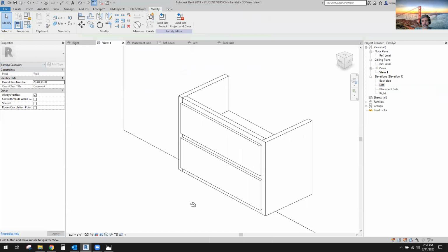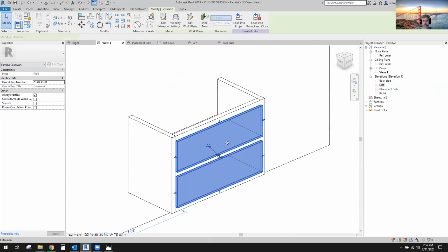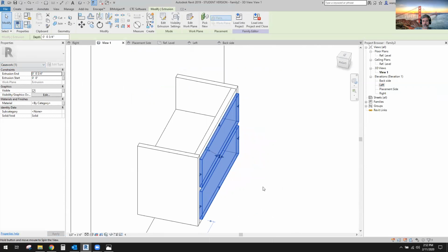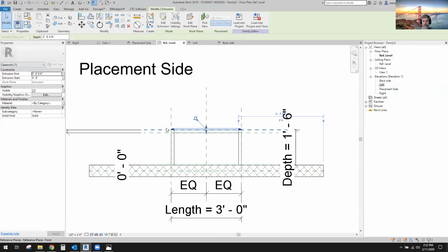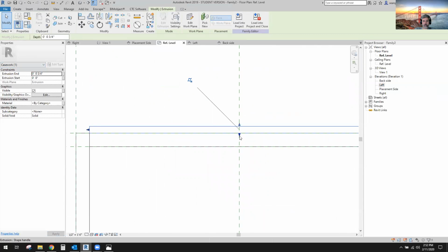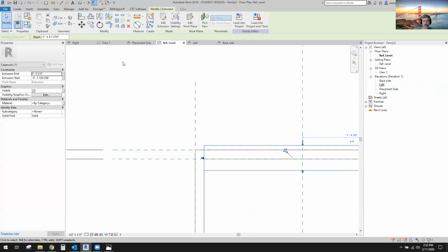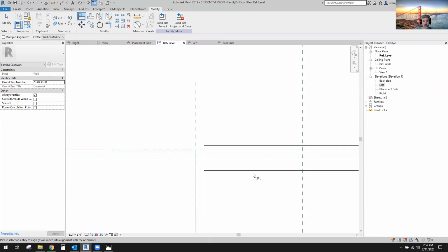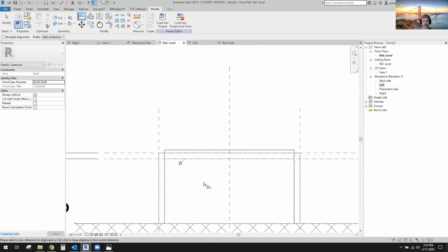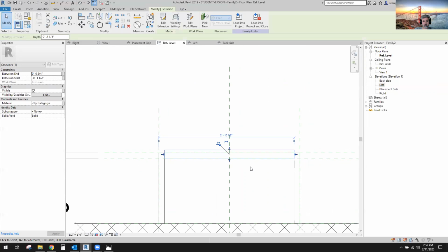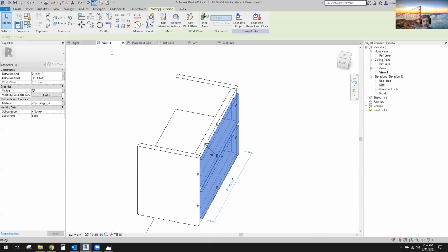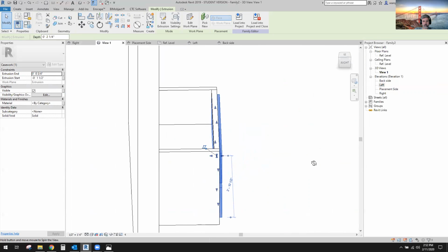Yeah, I think that feels a little nicer. Okay, it's not currently locked to any plane, which means that if I pull on either of these grips, it'll pull in any direction. I don't want that. So let's look at the reference level and try to lock those down. Even though I'm drawing on the plane, it doesn't lock it to the plane. So I'm going to do the locking to the plane right now. Locked. Okay, and get this guy here. What is this piece?